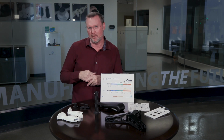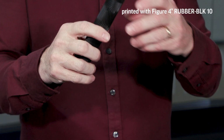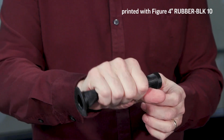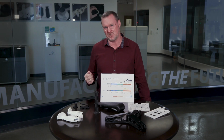And then of course the rubber. The rubber parts tend to be lower than the 500 megapascal flex modulus, and your rubbers are going to be some of your Santoprene and Buna-N type materials with, if you look at the Shore D values of where those are, the lower your Shore D, the more flexible, the more elongation you're going to get. So your rubbers are going to kind of land on that end of the Flexural Modulus spectrum.